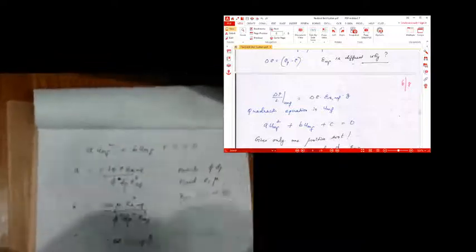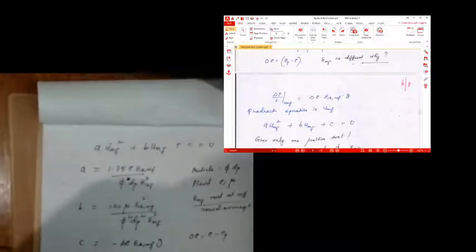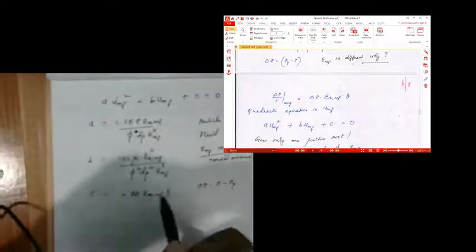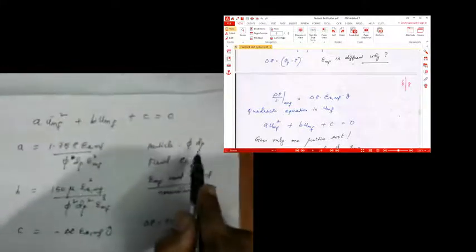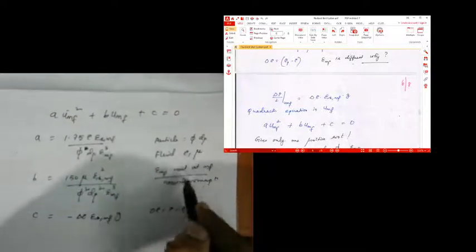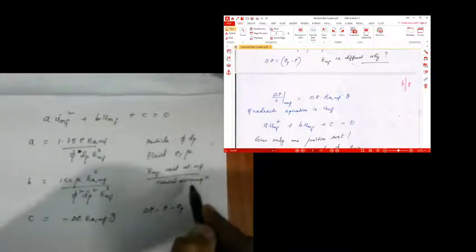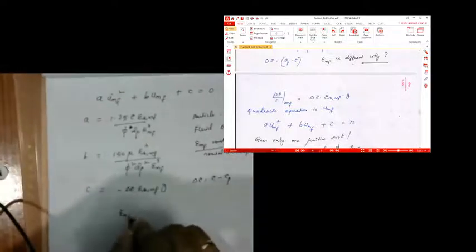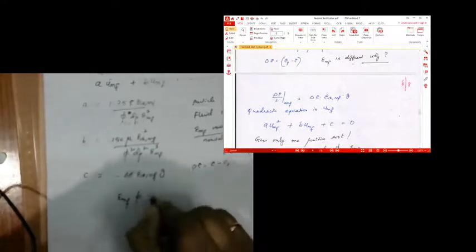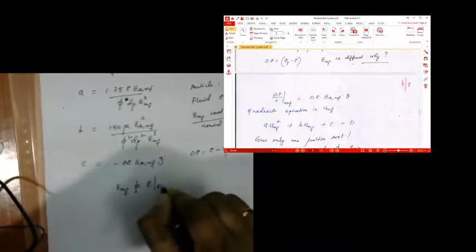Of these, only one of the roots would be the positive value, which will indicate the minimum fluidization velocity. So it is indeed possible to calculate this transition UMF knowing the particle properties, fluid properties, and an experimental or assumed value of minimum fluidization voidage. So this minimum fluidization voidage is not equivalent to the voidage of a fixed bed.